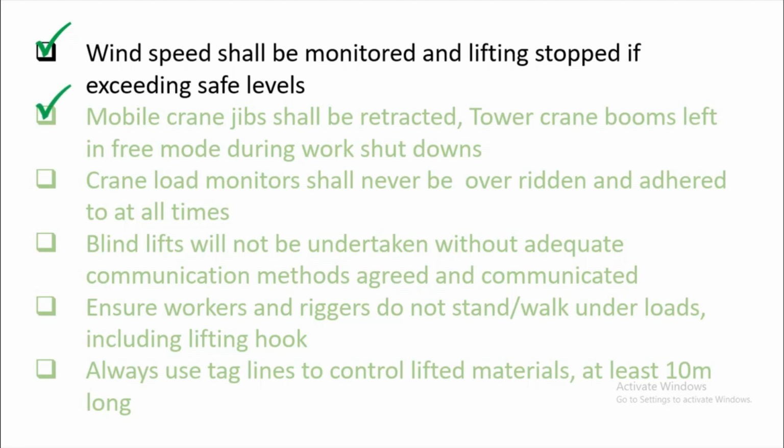Like for example, in the UAE, in Abu Dhabi, you need to stop all the lifting operations if the wind speed is around 38 kilometers per hour. Or in Dubai, you need to stop if the wind speed is reaching 39 kilometers per hour. Sorry, the unit is per hour.